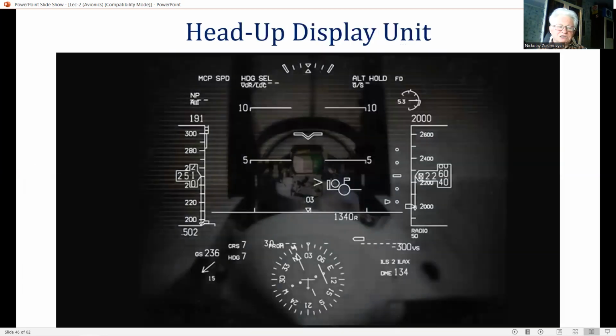The display drive unit contains all the display drive electronics for the HUD CRT, including the high voltage and low voltage power supply unit. High linearity and high bandwidth X and Y deflection amplifiers are required to meet the HUD accuracy and cursive writing requirements. Video interface electronics are incorporated in the display drive electronics for the TV raster mode.